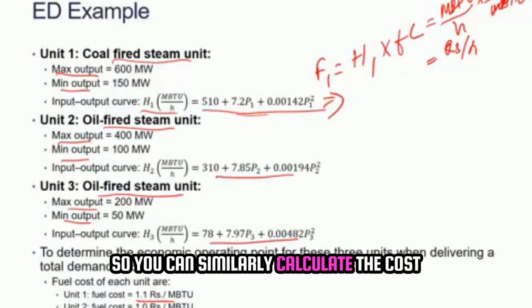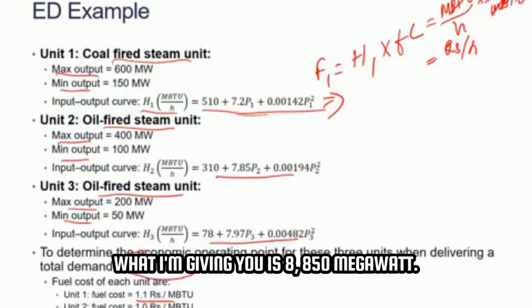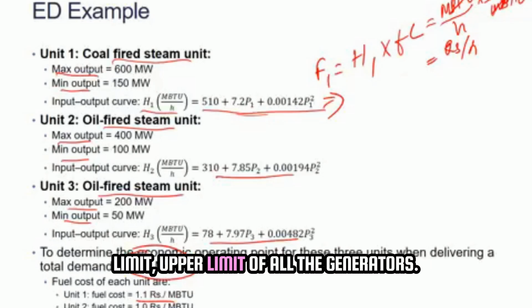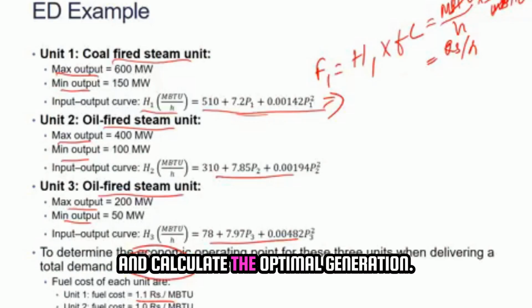So you can similarly calculate the cost of all the plants, and the demand I'm giving you is 850 megawatt. So basically there are three generators, PG1, PG2, PG3. The demand is 850 megawatt. You have to calculate the lower limit and upper limit of all the generators. You have to run the lambda iteration method and calculate the optimal generation.